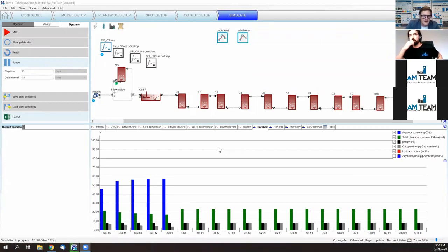Yeah, a very interesting question. Well, then we have to probably look at mitigation strategies. If bromide levels are really high or they spike from time to time, for example, they can be very well correlated with conductivity. This is what we have seen at a couple of plants. There are mitigation measures that you might be able to test. For example, the addition of hydrogen peroxide to suppress the bromate formation, which we have seen works quite well when bromide is high. Again, it depends on the matrix, but it works quite well so far, we have seen. Or some other strategies, like the dosing of other chemicals. But there are definitely things you could be looking at.